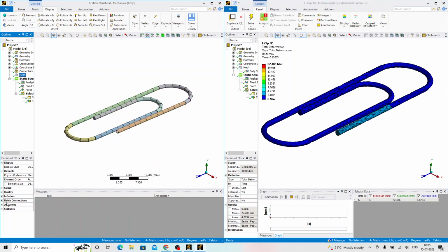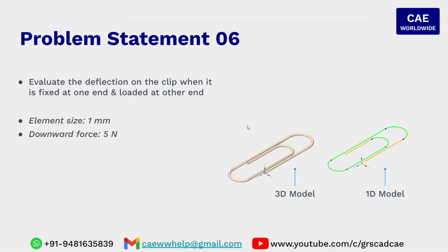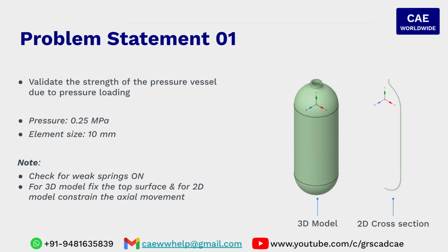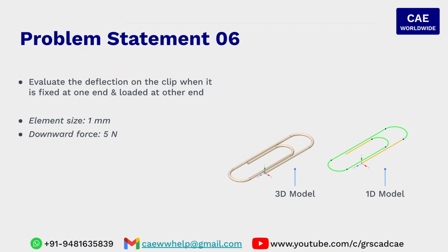We click on the mesh over here, and the statistics or the node count is just 135. In the 3D case, the node count is 4000. Is it not? It is always better to simplify the models, which can be modeled very systematically by considering special elements, than doing a default mesh. So the overall understanding of this entire session is we have learned how the geometries can be simplified and only the cross sections or the simplified geometries can be considered for the analysis.